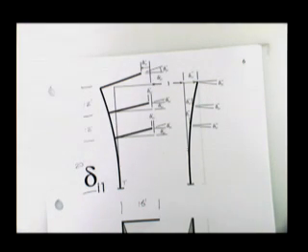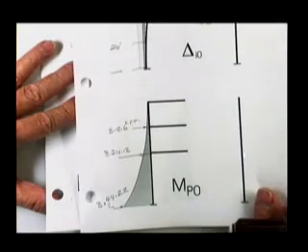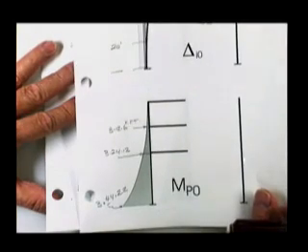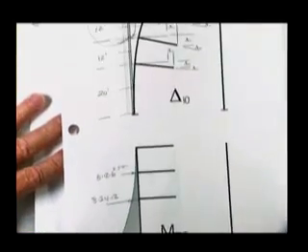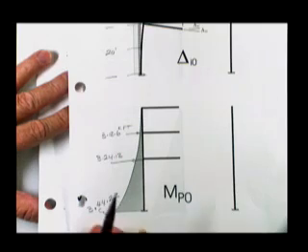It's a mess. Yes, sir. Okay, on your moment diagram, if you were to flip the side it's on, would you just change the sign? Absolutely. But when you do that, you have no choice but to flip this one also. You have to flip them both. In other words, if you say, I'm not going to plot things on the tension side anymore, I'm going to plot them on the compression side, you have to do that for everything.